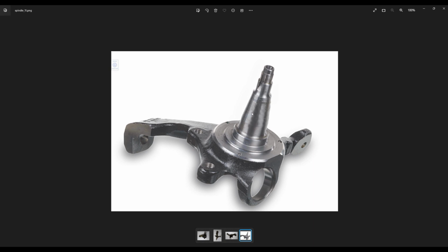When I start reverse engineering, I always ask myself what are the primary surfaces that need to be accurately reconstructed and which are not so important. If you look at the screen, this is where this part will be mounted and connected to the other parts in the assemblies. This is really perfectly flat here, and everything else is casting. Probably when it was manufactured, they created this part roughly, and then with machining tools they just cut off material here. So before you begin you always need to analyze what your goal is.